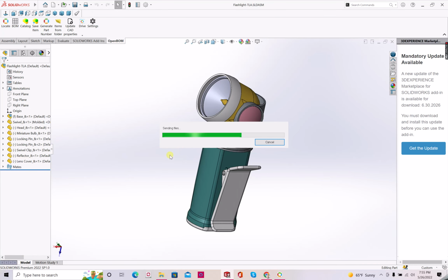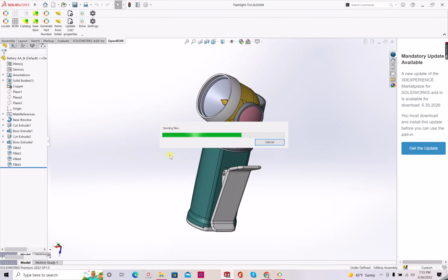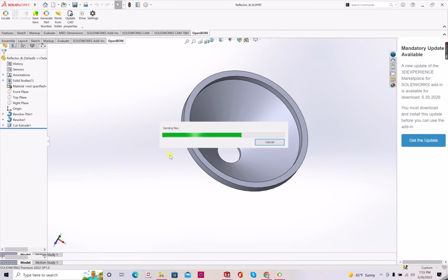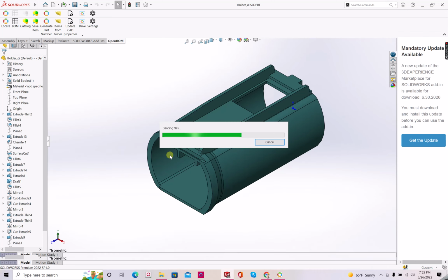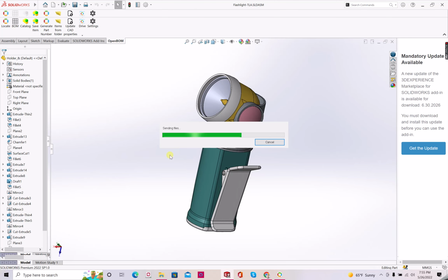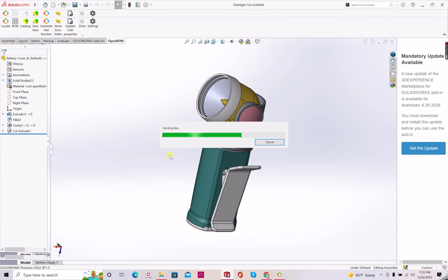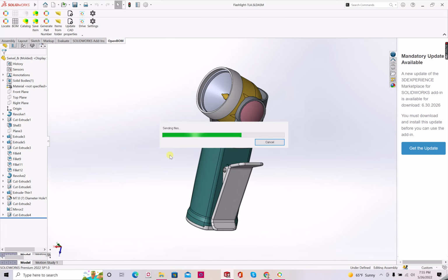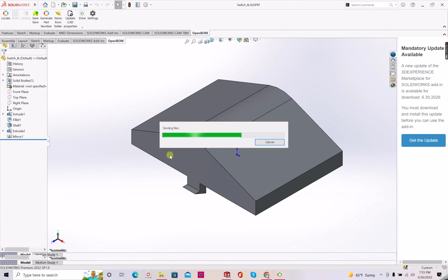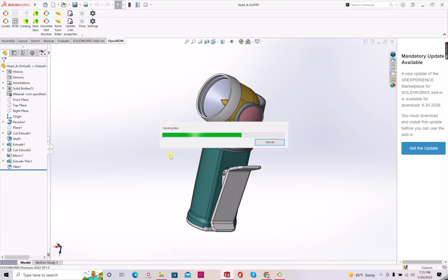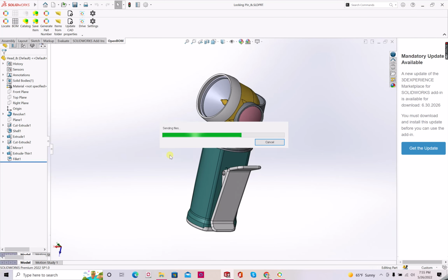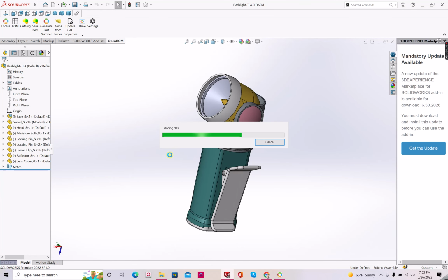These files will be attached to items in such a way that you will be able to store this information, and later when you manage item and BOM revisions, this information will be stored in the OpenBOM database. So you will have a full product record of all metadata and all file information. This information will be stored in OpenBOM.